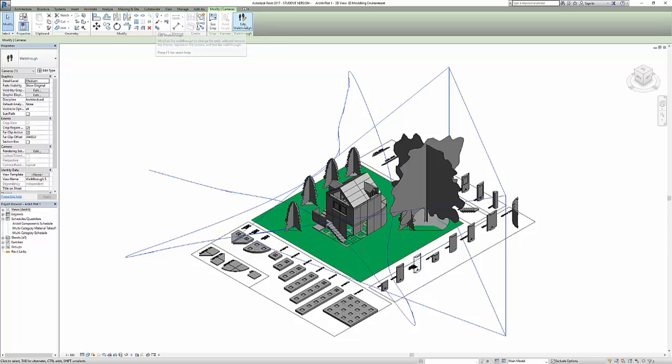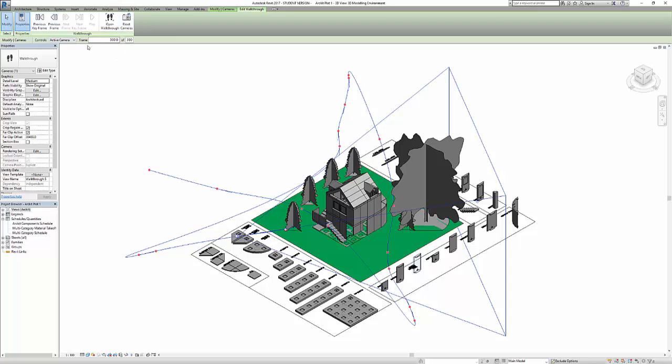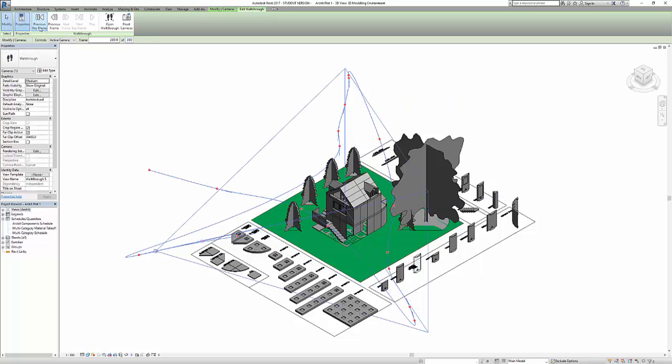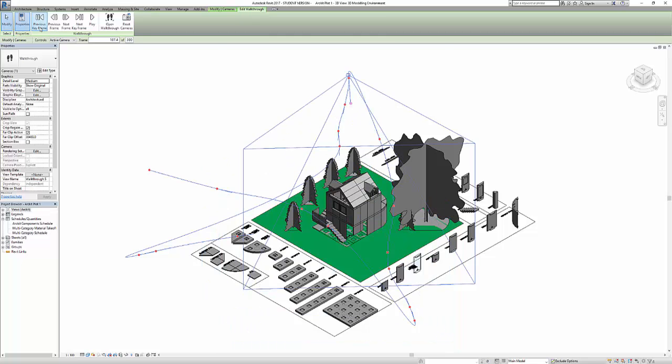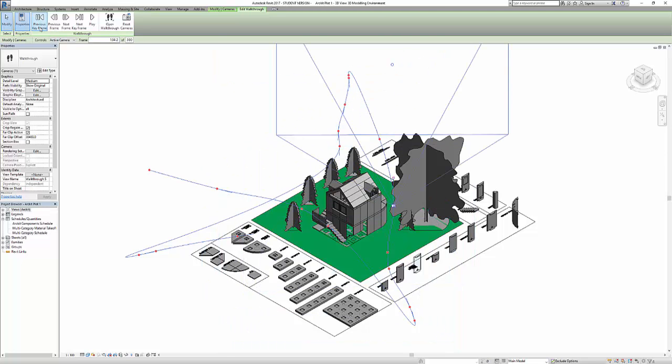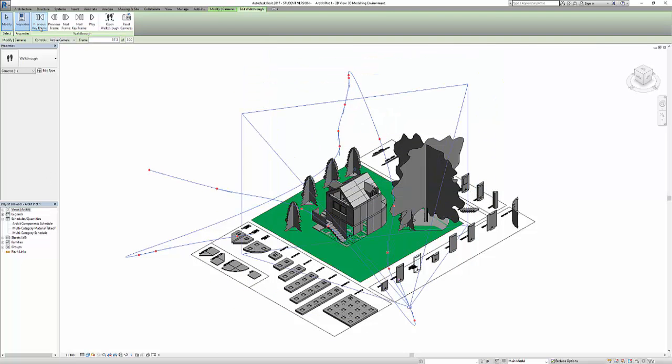Let's now choose from the top to edit the walkthrough. At the top here you will see that we have 300 frames and we are currently at position 300. So choose Previous Keyframe and you can skip back to the positions of the camera and see instantly where each one is. Each one of these can be edited again, but let's return to the start.